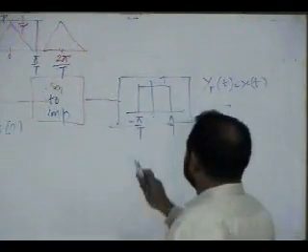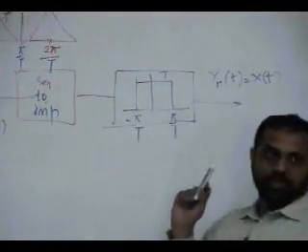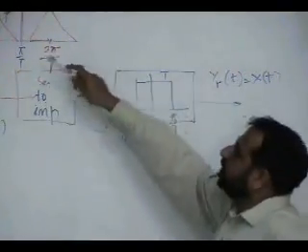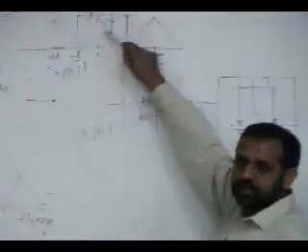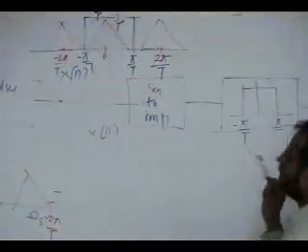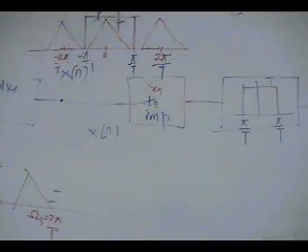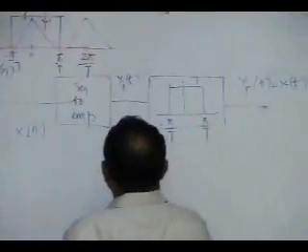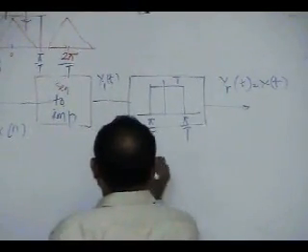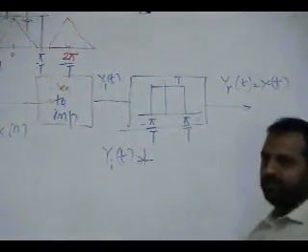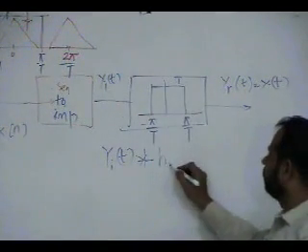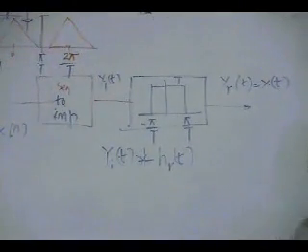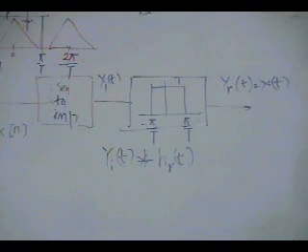Right? So passing through this in continuous domain, a low pass filter is multiplication in frequency, which is very trivial to visualize, but convolution in time. Right? So it means what I get here, let's say if I call this y(t), gets convolved with the Fourier transform of the reconstruction filter. Let me call this h_R(t).